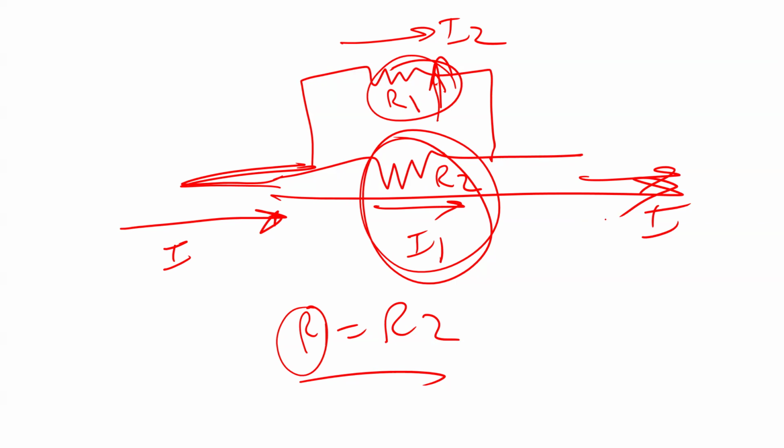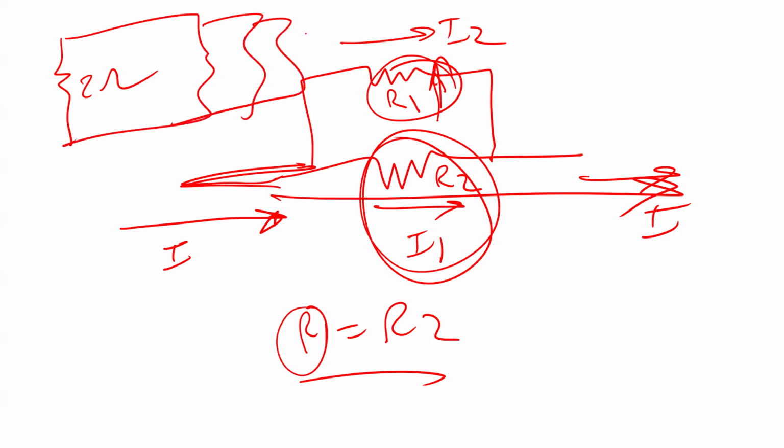So usually if you have two resistors in parallel this way, more current is going to flow in the branch that has small resistance. You understand what I'm saying? That's why, for example, I can have here a 2 ohm resistance. If I connect here multiple resistors, every one, for example, 1K, 1K, 1K, it's okay to assume all the current is going to go this way, and 1K compared to 2 ohms is practically infinity.